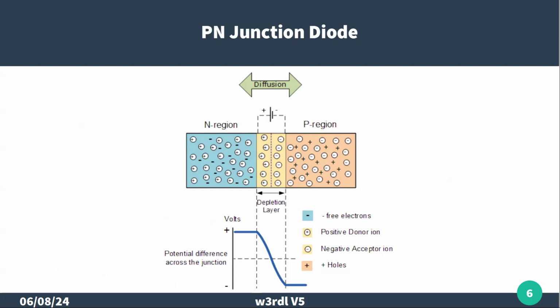When we apply that voltage in the positive direction, from the P being positive and N being negative, that depletion layer actually shrinks a little bit. And it allows, once you have enough energy to cross over that depletion region or that gap, it allows current to flow. When you reverse the polarity, it causes the depletion region to grow. So it makes it much, much harder to conduct current. Now, at some point, with high enough voltage, it will. And that's called the Zener effect.